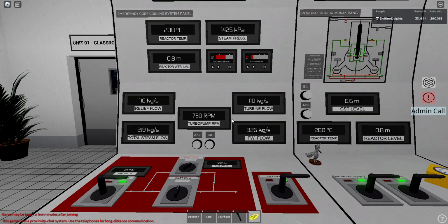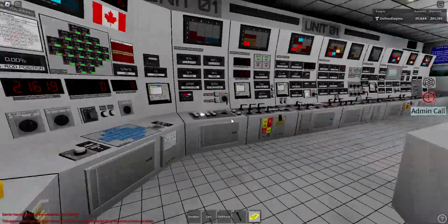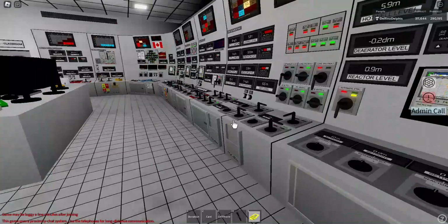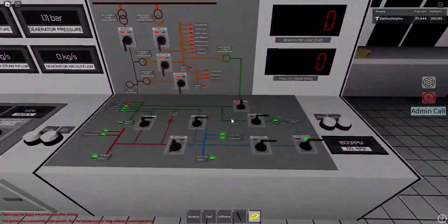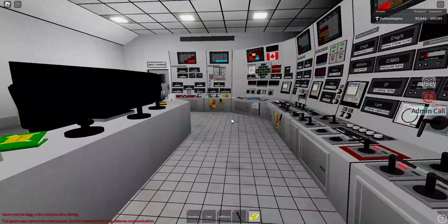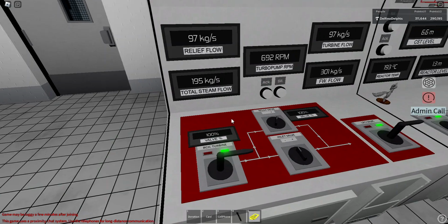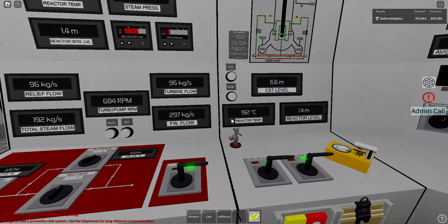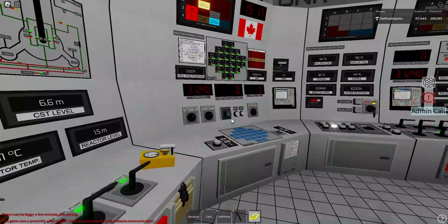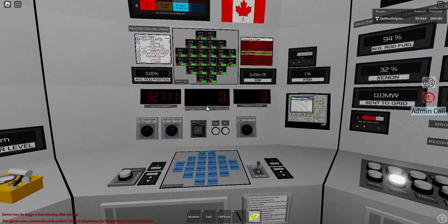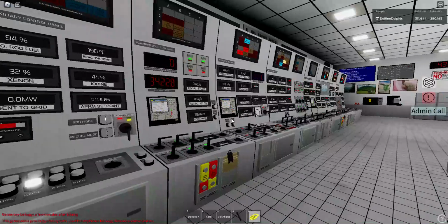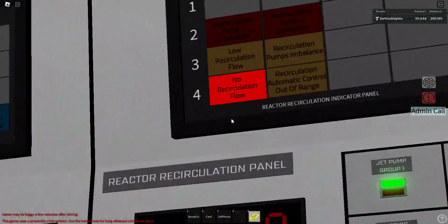So when it happens by surprise, remember that the priority is to get the lights back, start the diesel, and enable this reactor core isolation cooling to provide water to the reactor, which is still boiling. Of course, scram the reactor to 0 if it doesn't scram by itself.